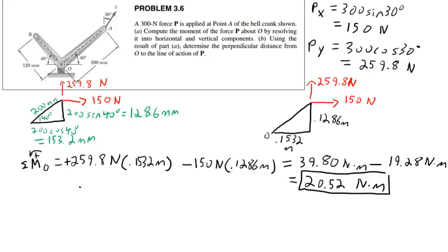All right, so what else can we do? Well, in part B, it's asking us for the perpendicular distance. Yes, the question was what is the point 1532? This is the length of this triangle here. It's the horizontal distance from point O to point A. See this triangle, 40 degrees here, the hypotenuse is 200. The x component is going to be 200 cosine 40. Okay?